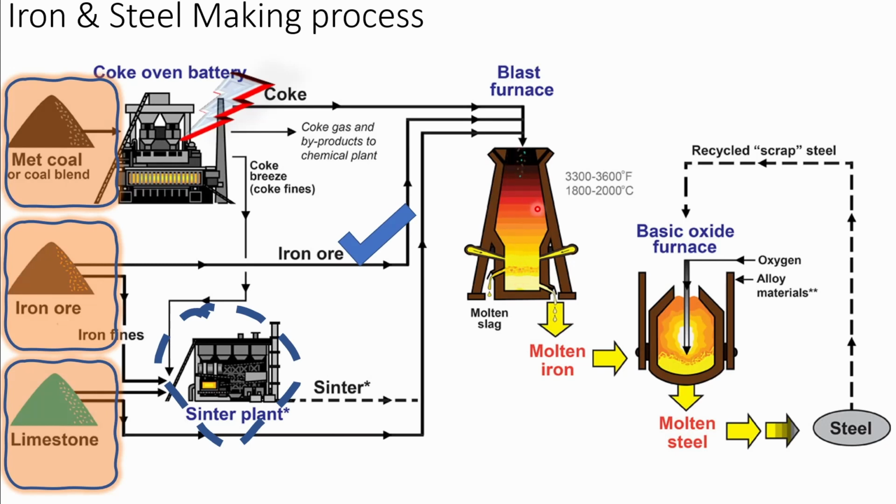A few feet below the feeding area, the temperature could be about 200 degrees Celsius. As the material comes down, during this process, a lot of air is blasted, and as there is a mix of coal, iron ore and limestone, it creates a kind of heating element. So the more the input gets heated, the iron reacts with the help of all this heat and the air coming into contact, at around 1500 to 1700 degrees.